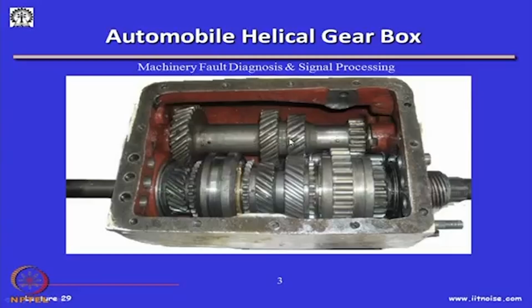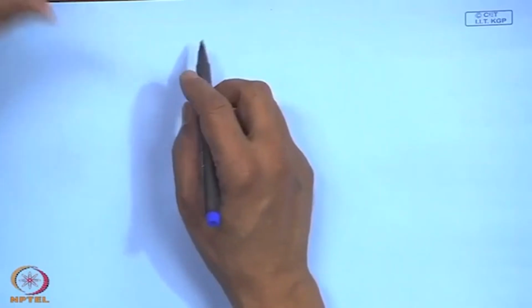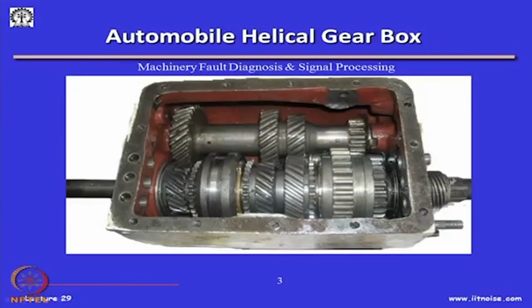This is the counter shaft, and these are again the gears, and these are what are known as the synchronizers, which can be shifted while you shift your automobile gears, so that appropriate gears will mesh, and then we will get a speed reduction. And this is another gear. So, in an automobile gearbox, we have synchronizers, and I will show you how a defect can arise, because each of these gear teeth will deflect under load, and they will get heated up because of the friction.